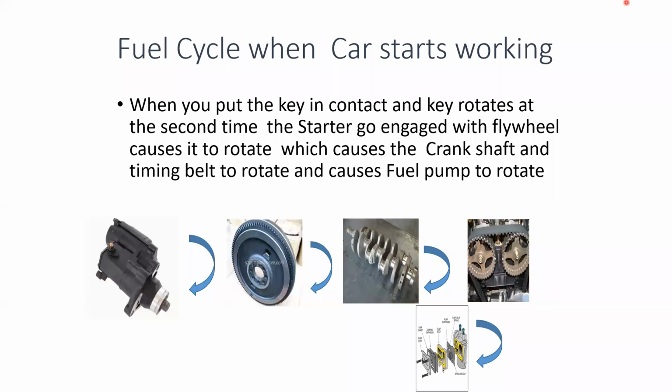Right. So once you start the engine, we call it cranking the engine. So we turn the key and we start cranking. The starter motor rotates, and in turn it will rotate the flywheel. The flywheel will rotate the crankshaft. The crankshaft will start moving the pistons and valves.